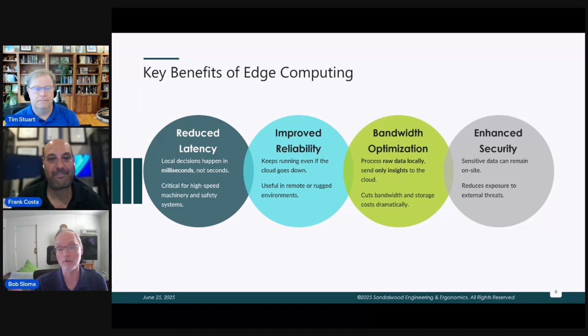Yeah, the other thing you definitely can do at the edge is, instead of collecting just raw data and sending it on, you can use the edge device to do the normalization of that data, right? And the standardization of the payload that gets sent onward to other systems, like an MQTT broker, for example. Right. Instead of sending the raw data that's unprocessed and having to do it at a higher level in the architecture.